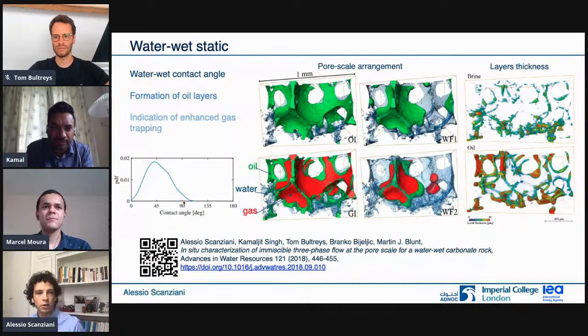For the geometric contact angle, we don't smooth the interfaces, but we have the segmentation in between, so this can influence the results. We have done some direct comparison with the manual measurements on grayscale images. So from the geometric contact angle point of view, we are quite confident that this is actually measuring what we see geometrically at the three-phase contact point.